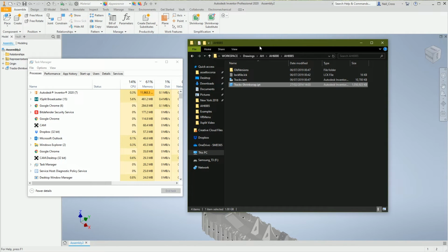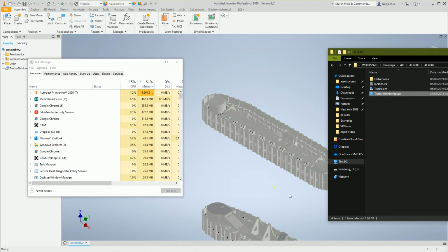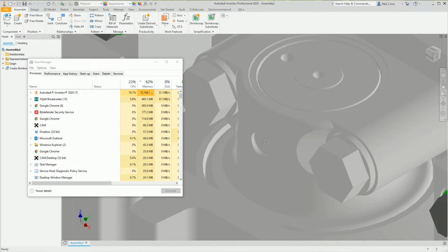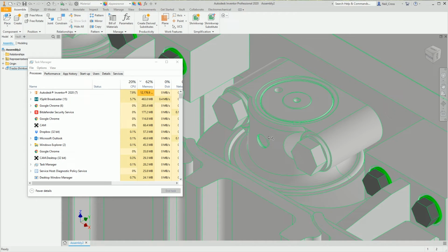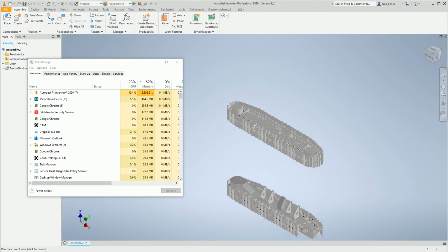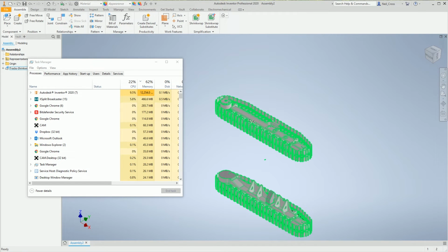And I've had it confirmed by someone, I can't remember who, but someone on the Inventor development team. The IPT file format, and this won't be just for Inventor, this will be for any CAD system, the single part format is never ever designed to host this much data. We've got an absolute massive colossal assembly worth of data wedged into a single part file. It's not supposed to be that way. Although Inventor can bring it in, it has a hugely hard time in handling it.